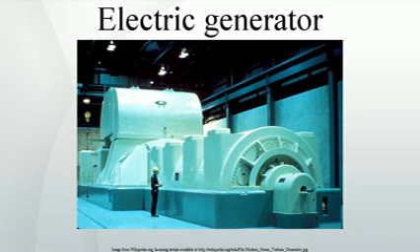As a result, the charging output of an alternator at engine idle speed can be much greater than that of a DC generator. Automotive alternators power the electrical systems on the vehicle and recharge the battery after starting. Rated output will typically be in the range 50 to 100 A at 12 V, depending on the designed electrical load within the vehicle. Some cars now have electrically powered steering assistance and air conditioning, which places a high load on the electrical system. Large commercial vehicles are more likely to use 24 V to give sufficient power at the starter motor to turn over a large diesel engine.